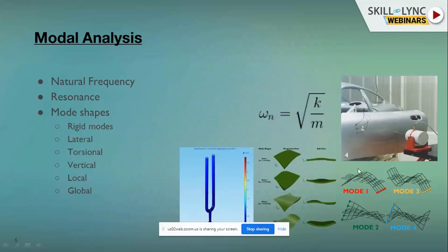The amplitude would be magnified to a greater extent, and the body attached to it, that is the seat, would experience very heavy vibrations, and that would cause great discomfort to the driver. This would then be the area of interest for the engineer to arrest the vibrations of this mode, either moving the fundamental frequency to a lower or a higher band, and then rerunning the analysis to see if the driver's seat is experiencing lower or moderate vibrations which are under the regulated guidelines.